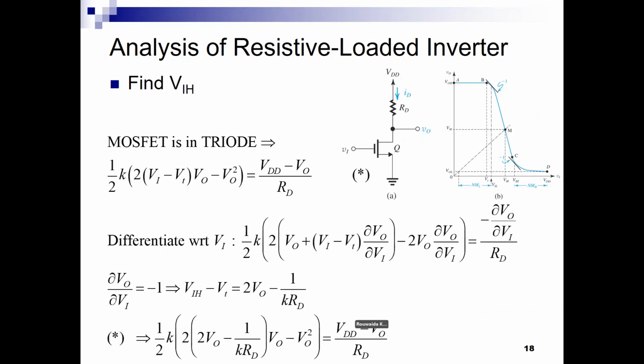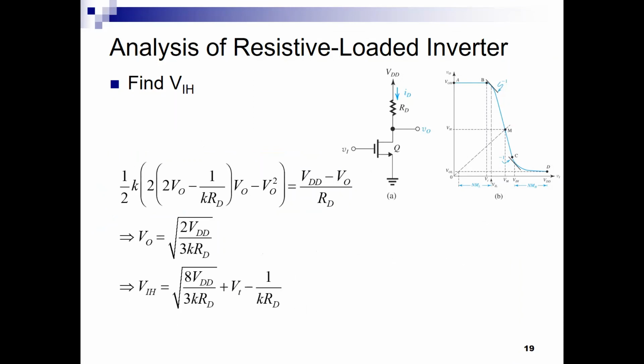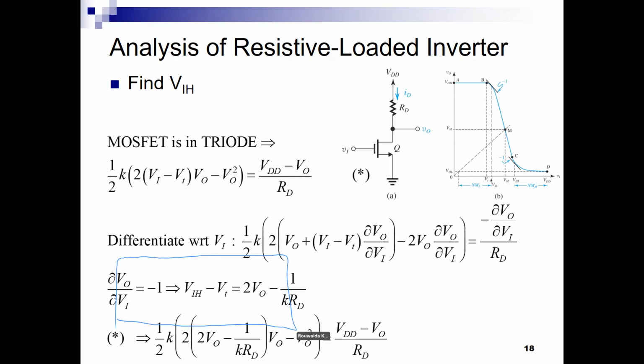Okay, now for VIH, it is this point, which is in the linear region. So we put IN equal to IR in linear mode, then take the derivative with respect to Vout of this expression, and substitute Vn equal VIH. It's a bit complex but we end up finding the expression for VIH. So be comfortable with what terms you can use. Okay, the relation between VIH and VO is there.